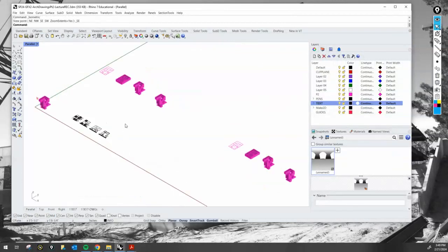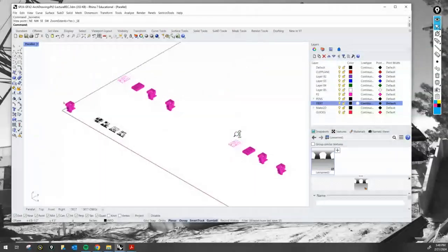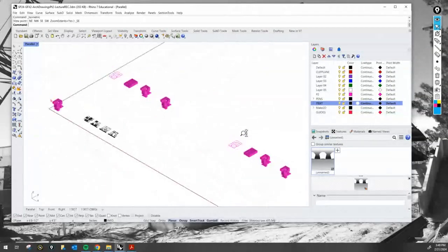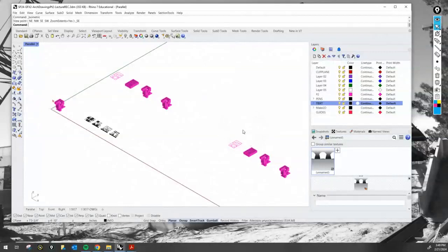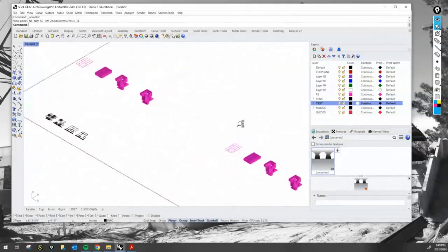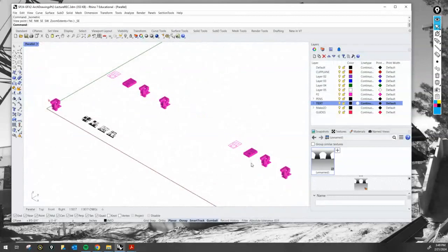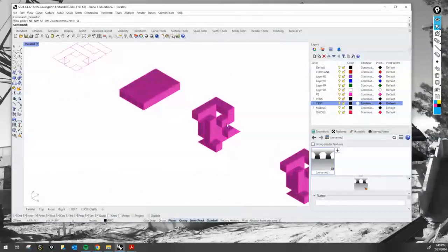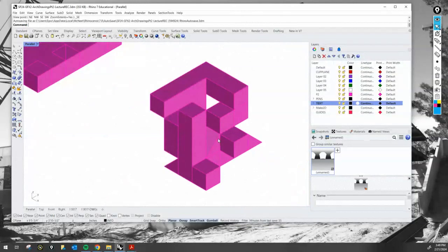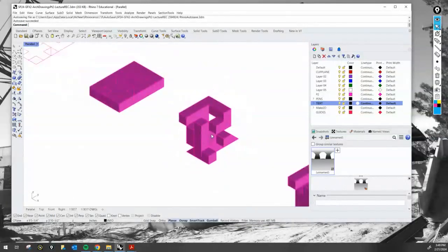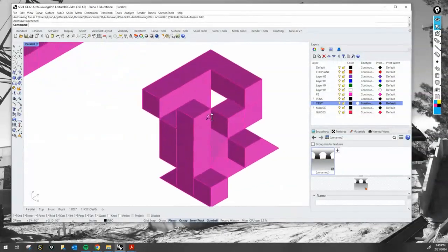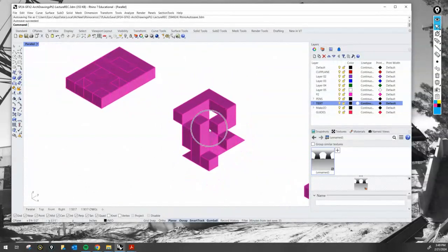So again, I'll set up the southeast, and if you need to navigate here, hold control and right click, and you can do what's called the dynamic zoom. We're actually going to be using this. Control key, right click, move your cursor up and down, and you get your dynamic zoom, which is in my opinion a little bit more precise than just the wheel, because the wheel does these clunky intervals, right? Click, click, click, click. But with the dynamic one, holding control and then right click, you can create a much smoother and controlled zoom in or out of the model.